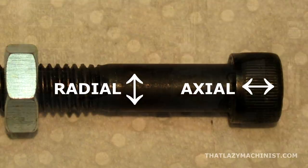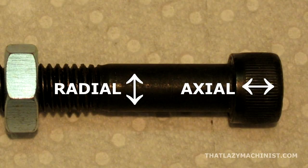Well, a 60-degree thread has 30-degree flanks, and a 30-degree flank that abuts up to a 30-degree flank on its opposing thread, well, pushes more axially, or pulls, than it does radially, but it still has some radial thrust and axial thrust, and that means that it will be easy to tighten down and will have a tendency to lock itself in place just a little bit, so it reduces the opportunity of loosening due to vibration. And that 60-degree is sort of a good mix for those two properties.